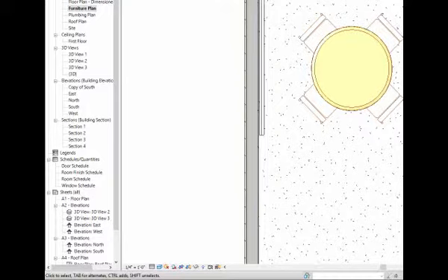I can use the Annotate tool, use the text under the Annotate tab. I can decide whether I want just a string of text that has no arrows, or leaders as we call them, or put a leader on that. I usually put a 2-segment leader. Let me just pull on down. I'm just going to call that whiteboard.